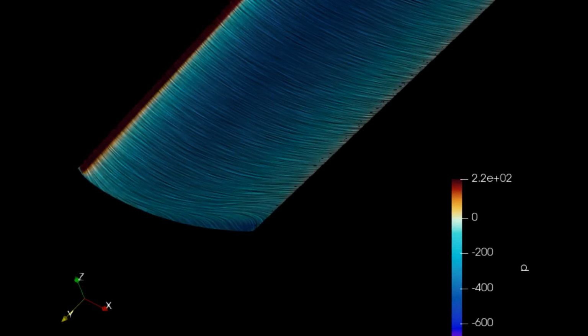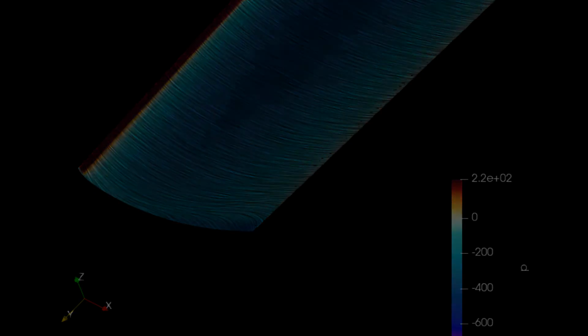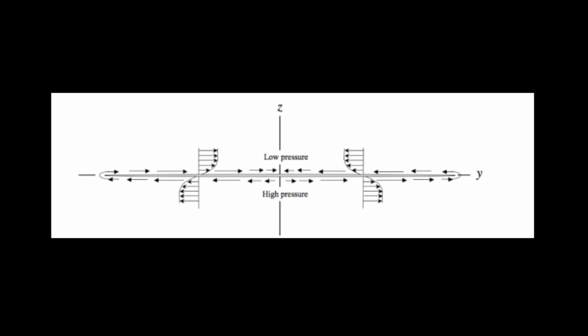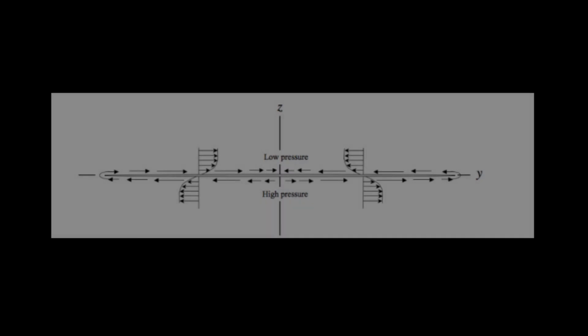The theory says that the efficiency of the wing should be substantially reduced because the vorticities at the end will produce no lift due to them being parallel to the airstream. Subsequently, this will reduce the lift on the wing surfaces inwards from the end. Another way to put it, using the idea of pressure and momentum, is that pressure will leak from the high pressure volumes to the low. The pressure gradient will determine how much momentum the air has and how strong the vorticity is.